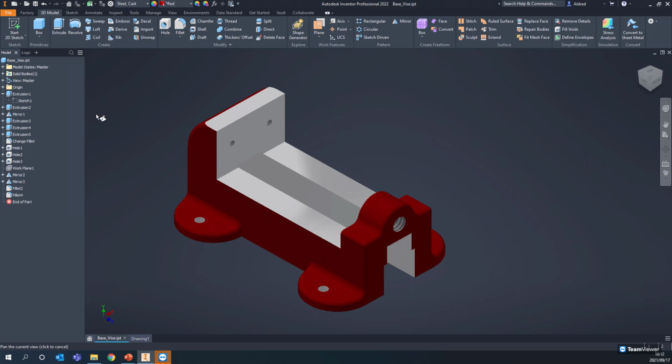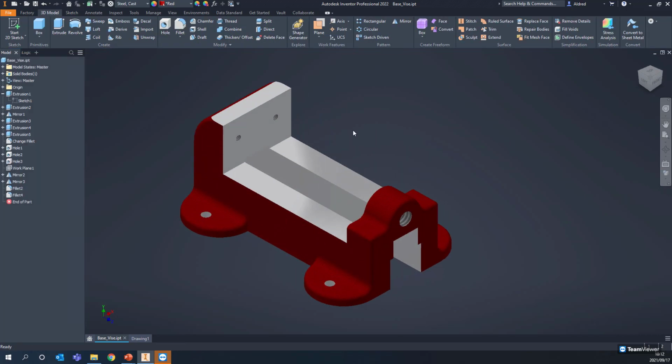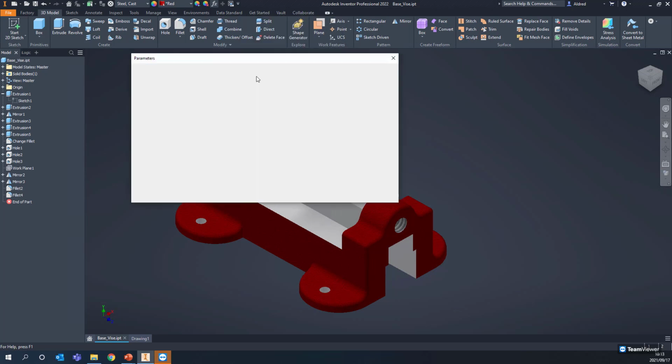Now, if I go back to the sketch over here and I'm doing something and I'm not really thinking, and I think, oh, delete that. Oh, wait, no, actually just leave it back again. Go off there. It's now D63. So model parameters, when they get created, if you delete them, they also get deleted. So they don't stay in the parameters for you to use in an equation for another dimension that you need. That is one of the downsides of model parameters. I'm not saying you can't use model parameters when you name them, but just note that.